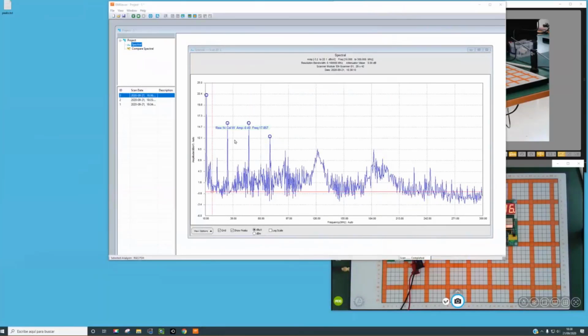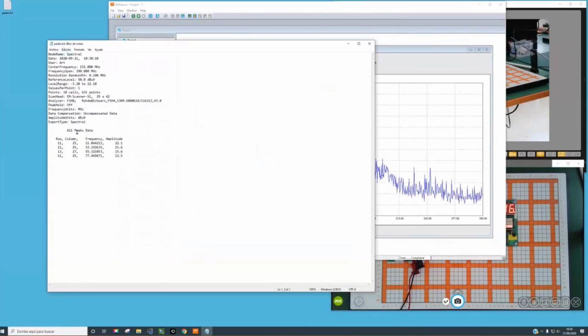And you can see that from my device, I have detected peaks at 11 megahertz, 33 megahertz, 55 megahertz, 77 megahertz, and only 4 peaks because I selected 4 peaks for measurement. And you can see that this is 11, 33, 55, 77. So it looks like the different peaks are multiples of 11. This is something like the main harmonic, the first harmonic, and the third, the fifth, and the seventh harmonic of the first signal. Okay, we will understand now specifically why this happens.